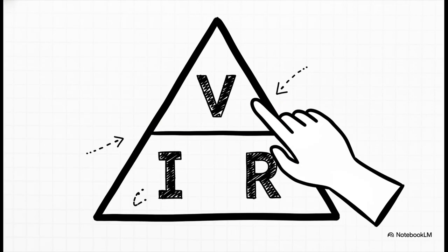And hey, if you ever forget how to rearrange the formula, and we all do, there's this fantastic little trick, the Ohm's law triangle. It's so clever. You just cover up the thing you're trying to find with your finger. So say you want to find the current, which is I. Cover up the I, and what are you left with? V over R. It's brilliant.